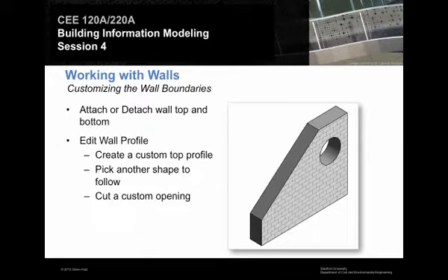With any luck, we will also get to what I hope will be the last topic today, which is a little bit more on schedules. Within the notion of schedules, what I want to show you is how you create the basic schedules, a door schedule, a window schedule, things like that. But also, there are two main things you want to be able to do to enhance a schedule. One is adding some sort of subtotal or grand total, some sort of tabulator that will do the math for you. And the other is embedding a formula in the schedule so that, as opposed to just reporting the values built into the database, you can compute your own things, whatever it is you need.